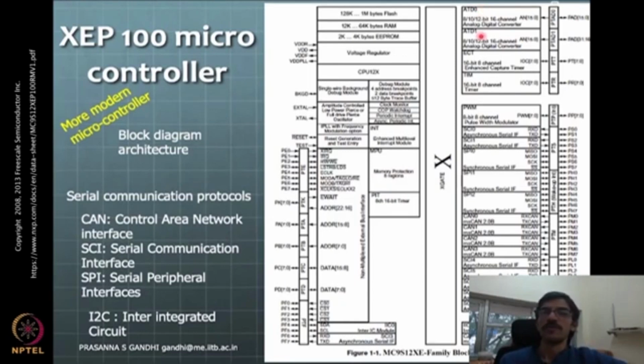So if you get into this kind of confusion, thinking these seem like 32 channels, you need to look at a little more detail in the data sheet, and you'll get to know that there are actually only 16 channels that can be programmed. Like that one can see there are only 8 motors that I can run maximum through this XCP100. So there are 8 PWM channels to run my 8 motors.